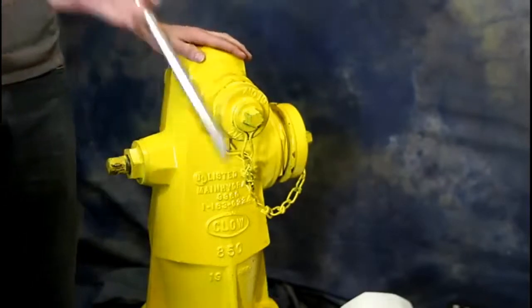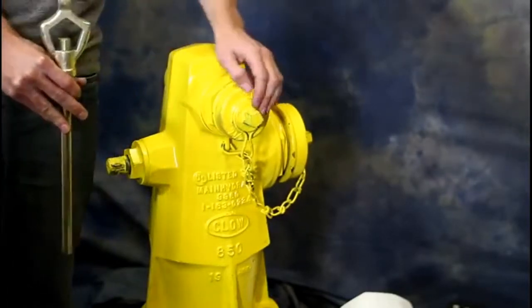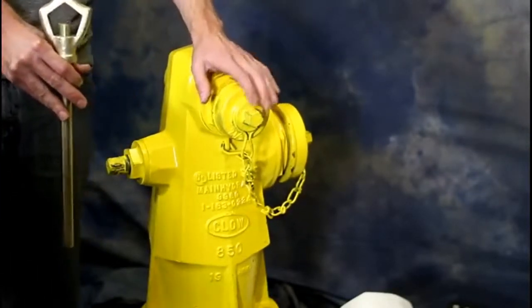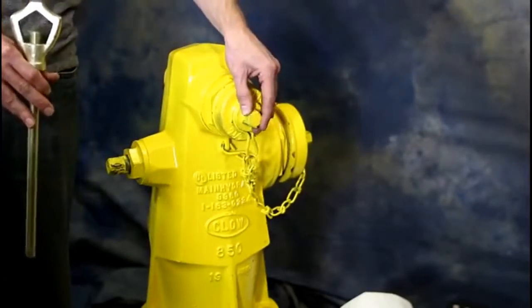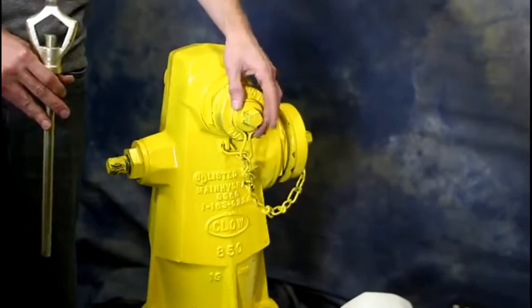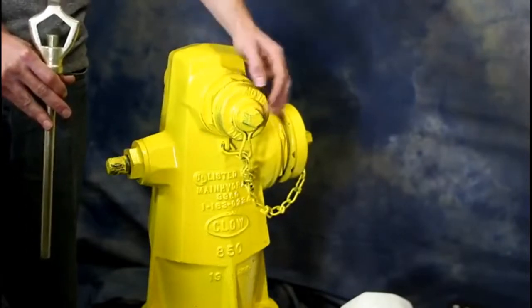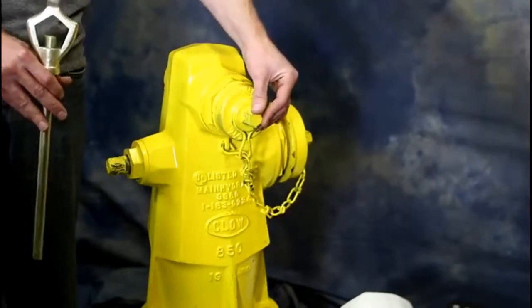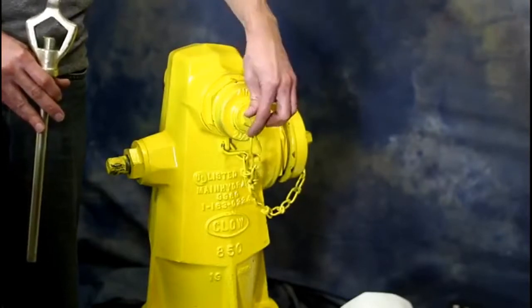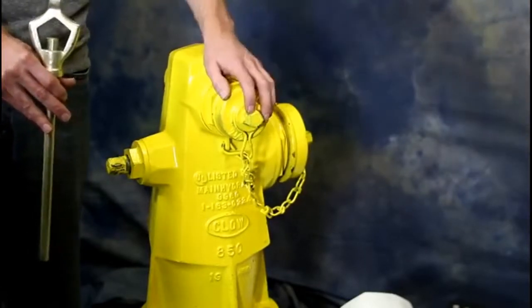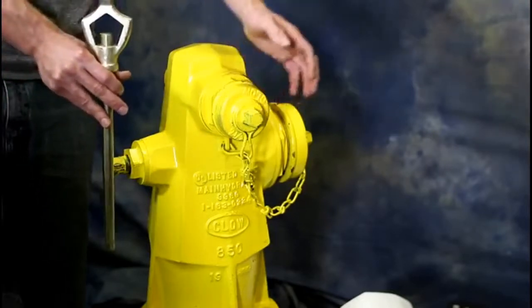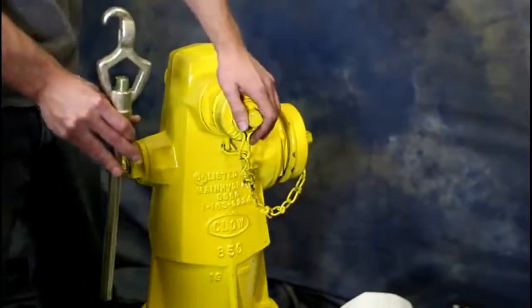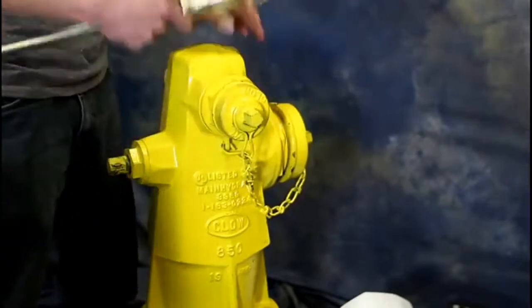Next, you're going to have the correct tool for the job. You notice these are 5-sided bolts. It is not a 6-sided bolt, which means your wrenches, your vice grips, pliers, channel locks, things like that are not going to work on this. If you try to use them, you're going to strip this right out. It's copper, so it will strip very easily. You do not want to get caught by the fire department, fire marshal, or city water guys without the right tool. They're not going to be happy.